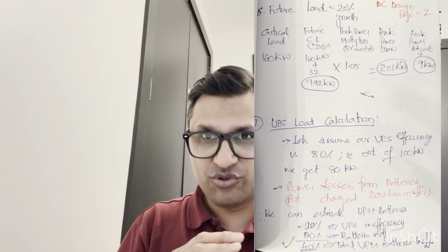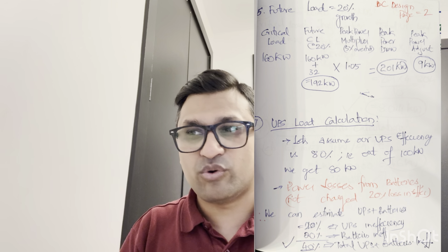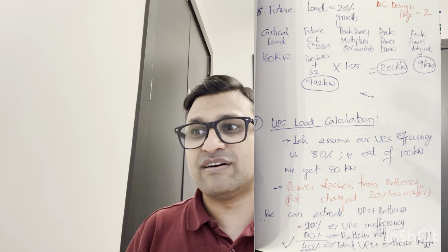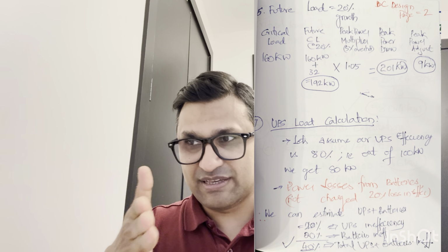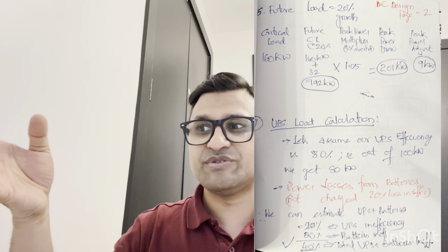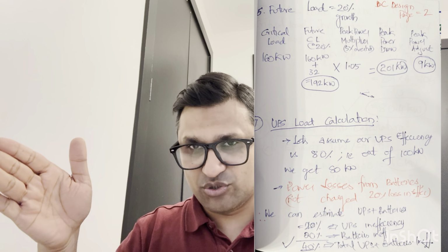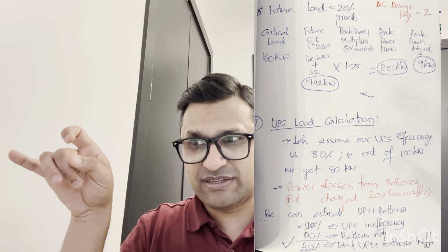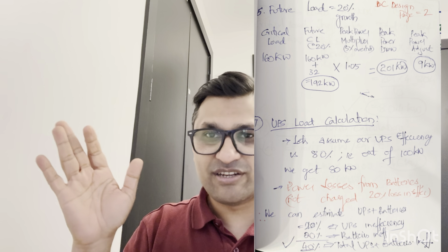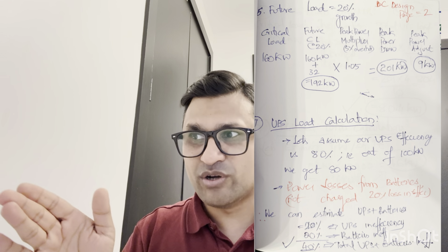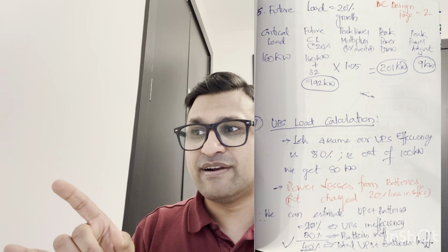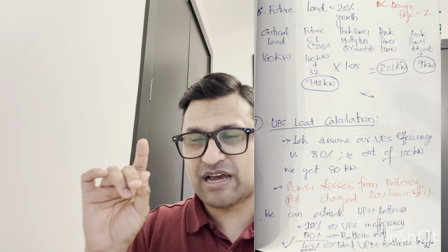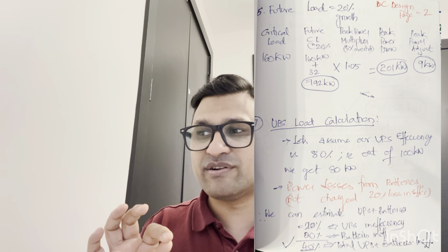And then the next is the future load. If you're assuming a growth of about 20%, keeping that in mind, we have a critical load of 160, and we are adding a future load of 20%. 160 plus 32 kilowatts is 192 kilowatts, because you multiply 160 times 20% to get 32, so it is 192. 160 plus 32 is 192 kilowatts, and you have a peak power multiplier. It's 5%, so it's 1.05. You multiply 192 kilowatts times 1.05, which is about 201 kilowatts.